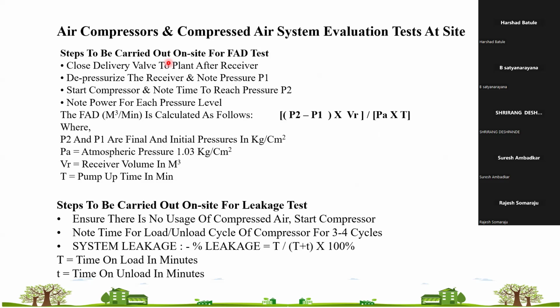Then there are methodologies of evaluation at site. There are two tests to be conducted during your assessment. One is the free air delivery test, and the other is a leakage test.